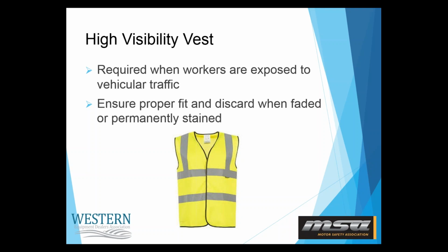So using a high visibility vest is part of the solution, but so is using a designated signaler, traffic control plan, routes in our parking lot, speed limits. These are all ways of dealing with vehicular traffic at the source, as opposed to just wearing a high visibility vest. So the vest is part of the picture, but there is more to it.